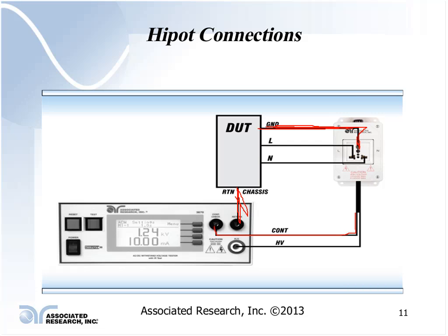The problem with that is if the resistance of your ground circuit is actually too high, then in some cases you could never pump enough current through that ground circuit to generate a fuse or circuit breaker failure should the insulation within the product itself fail.